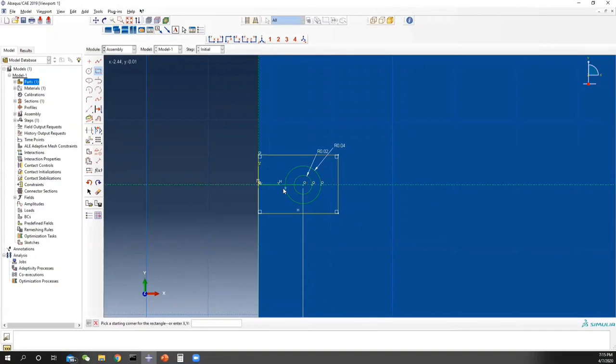we draw a rectangle just for the mesh. So use the dimension tools. For this line and this line, let's just make the dimension 0.06. Similarly, this one, let's also make it 0.06. And then the distance between the very right end and the first construction line, let's make it 0.2. Oh, sorry, 0.2.